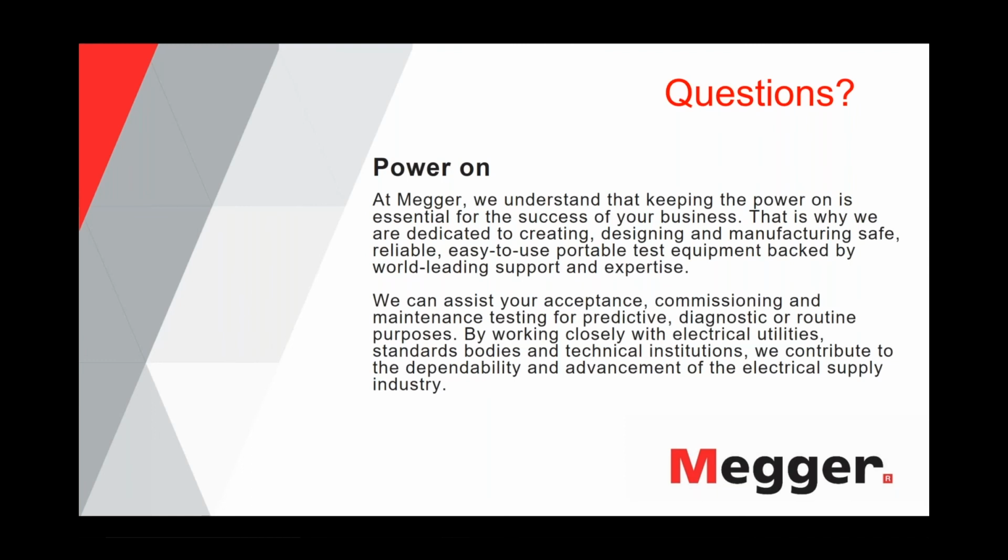All right, thanks. Robert, can you explain why cosine waveform cannot be used for testing? Yes. So, well, it can be used for testing, just not for tan delta. As Henning already explained, with the cosine rectangular waveform, you have an advantage that you are able to measure leakage current. You cannot measure leakage current with the sinusoidal wave because there is no leakage current defined. At any point of the curve, you have a different gradient, so you cannot define this.